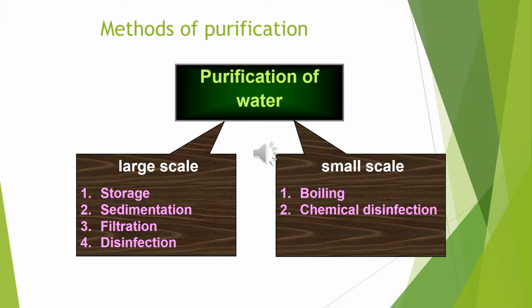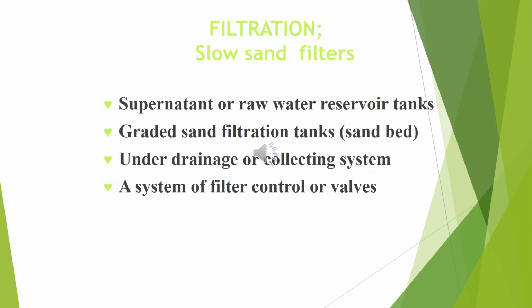Now, next coming to the filtration. Filtration is the second stage in the purification of water, and it is quite an important stage because 98 to 99% of the bacteria are removed by filtration. Filtration of water, as I told you, is done by slow sand filters and rapid sand filters.